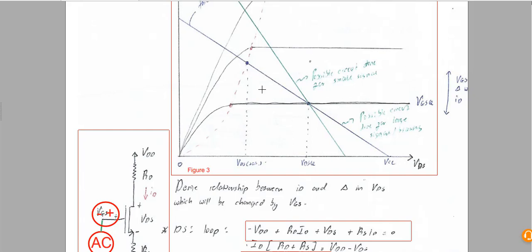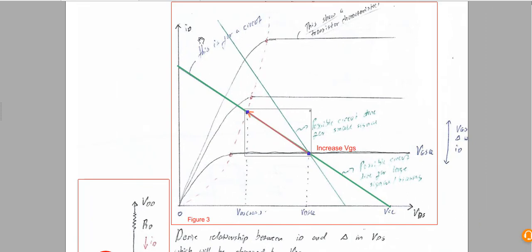But it won't be like that forever. Don't forget, as VGS changes ID, ID changes VDS. So when VGS increases and ID increases, our VDS will decrease on this trajectory and hit this point. Concurrently, as VGS decreases, it will decrease ID, and that will increase our VDS.